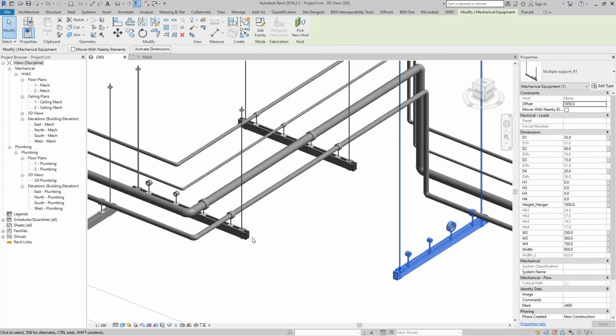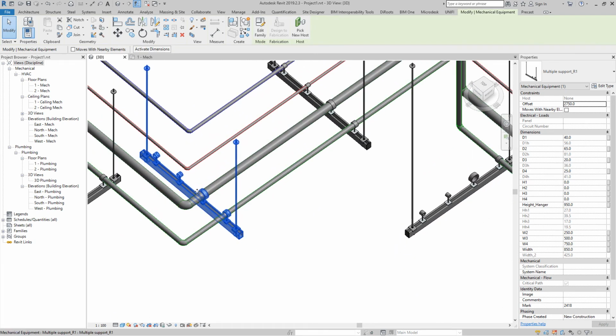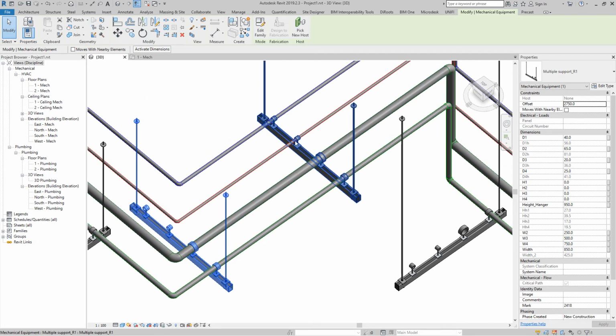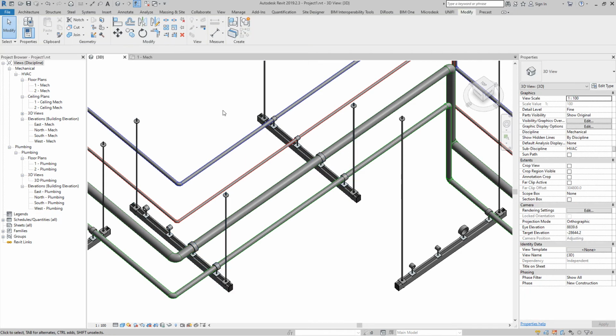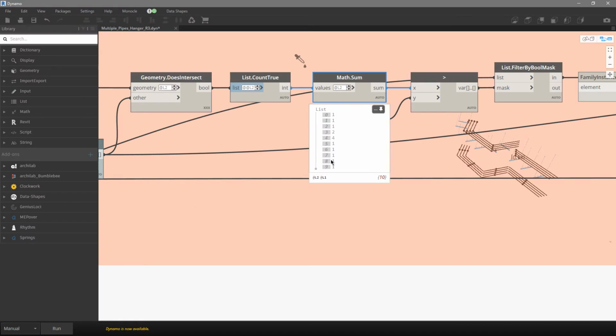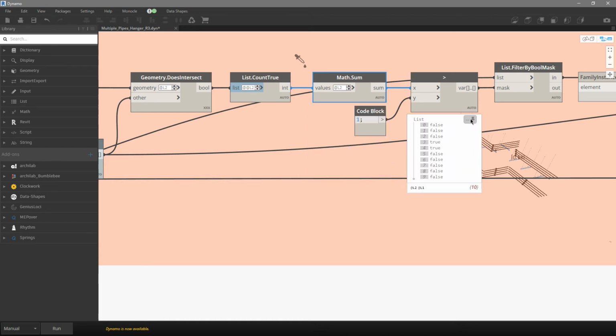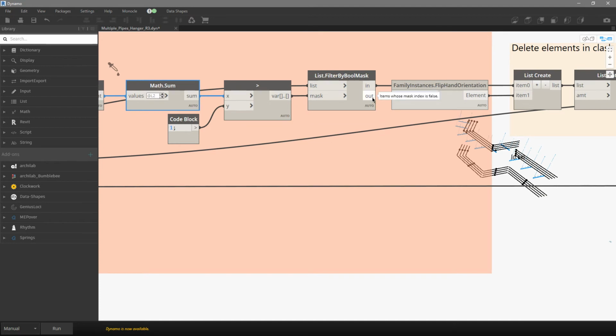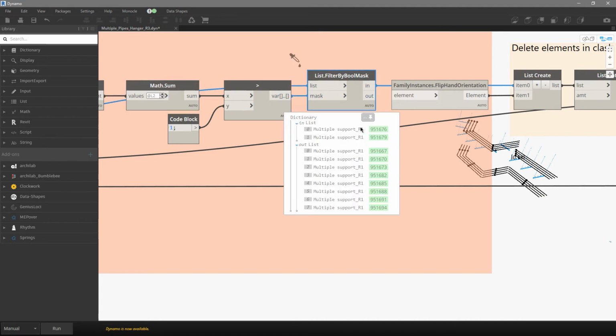It is not good when we do not have one, which is a signal that we need to flip a family, and we don't have alignment of 4, 3, 2, 1, whatever we did select as a number of parallel pipes. But okay, then we will perform some additional check and we will need to delete this hanger over here. For all those hangers which have a collision number between the hangers and pipe 1, we will flip those families. So over here we do not need to flip the families for 2 hangers, but for those 8 we need